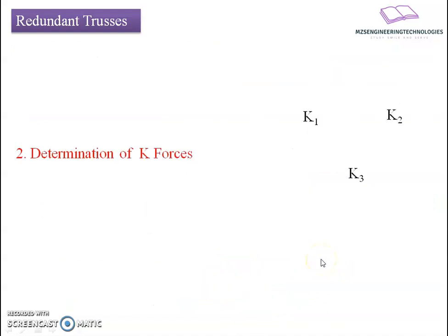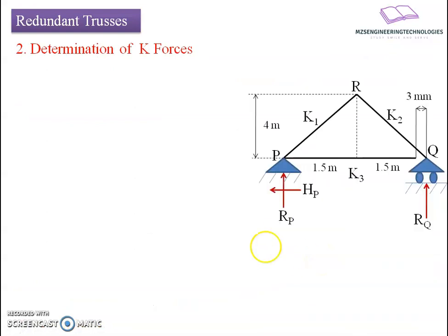Now if I move towards the estimation of the coefficients of forces, since there is no external load, we will apply a unit load at the joint R and try to get the coefficients of the distribution of the unit load among the other members. For that we have to go with joint by joint analysis.